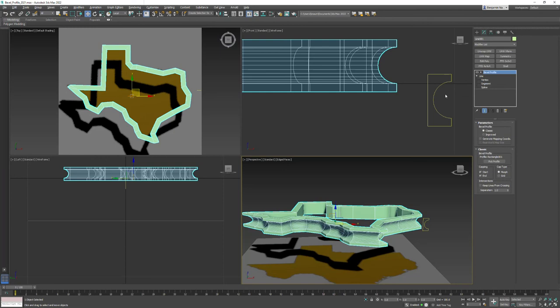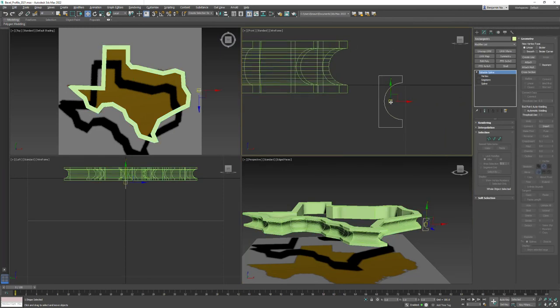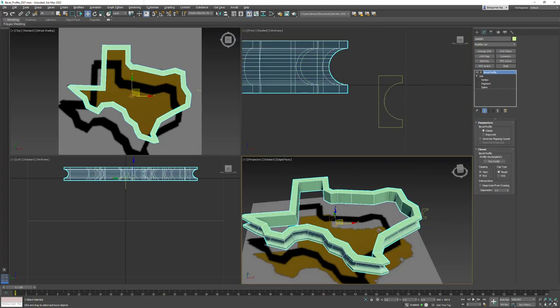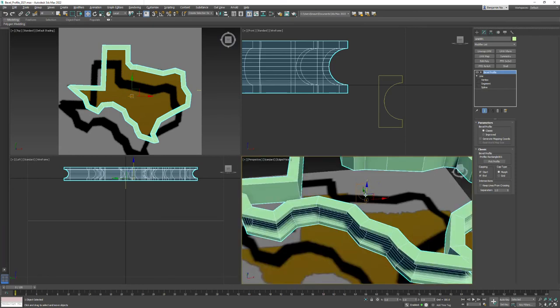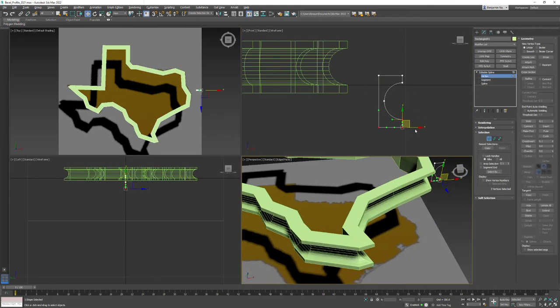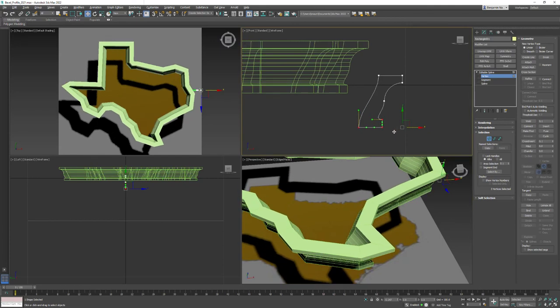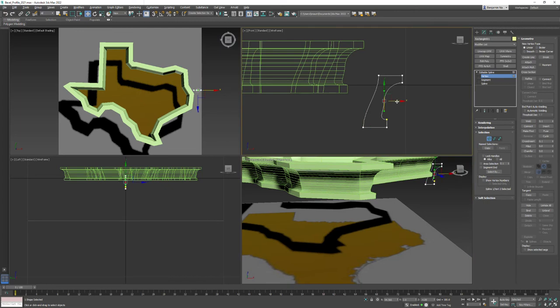Now we can also take this further. If we take this object, it gets added to this mesh. It's hard to zoom in on because it always stays really small, but at the origin of the model is a little crisscross. That represents the spline shape, and that's where your model is added, representative to that. So you could come back in here and grab vertex points and actually move them and adjust them because the Bevel Profile Modifier is referencing it. So we could take this and move these things around.